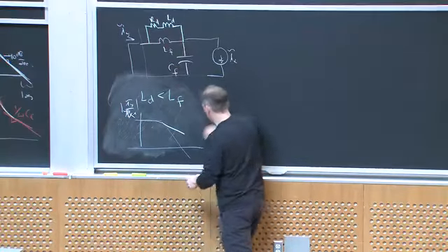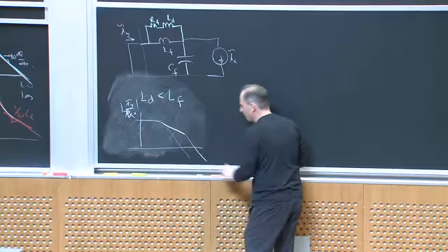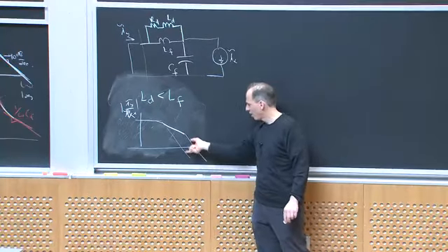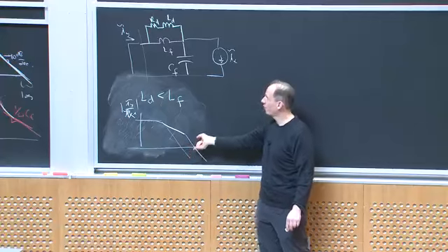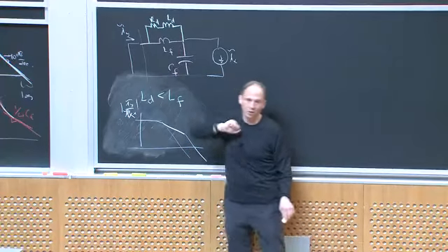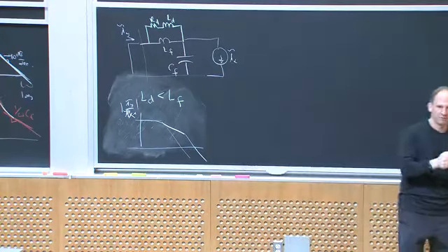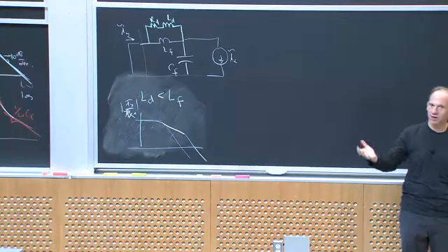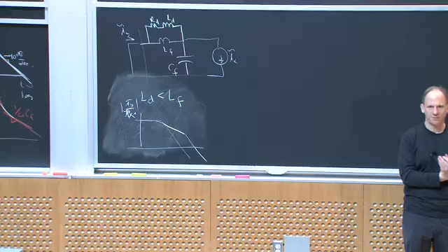And then once LD comes in, I'll start falling off, and I will eventually roll off at minus 40 dB per decade. But my roll-off's not going to be as good. So what do I have to do? I have to pick a correspondingly lower cutoff frequency to account for what LD is doing to my filtering. Okay? So that's the downside of this inductive damping scheme.